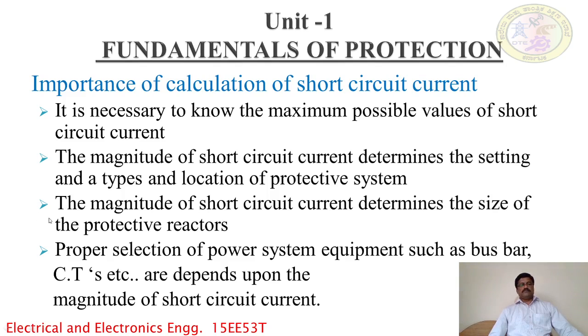So next one, the magnitude of the short circuit current determines the size of the protective reactors. So what do you mean by reactors? A reactor is a coil connected in series with the power system to limit the short circuit current.